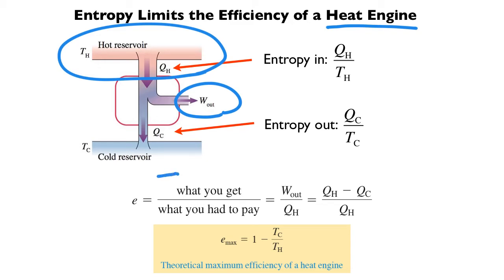But you're also going to dump a significant amount of heat into the environment. You're going to dump it into a cold reservoir, a place that is colder than the hot gases, which is pretty much everywhere. And you just dump it out the radiator in the front of your car. You are dumping heat into that cold reservoir, and you have to do that. And the amount that you have to dump is specified by the second law of thermodynamics.